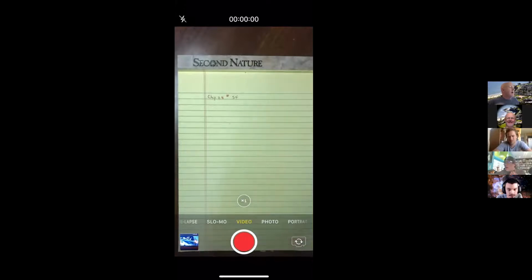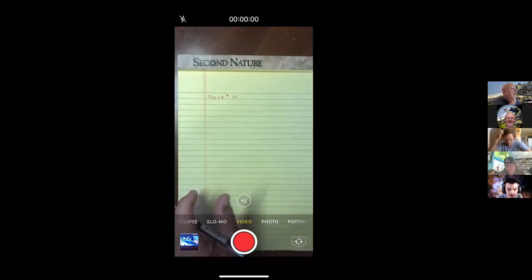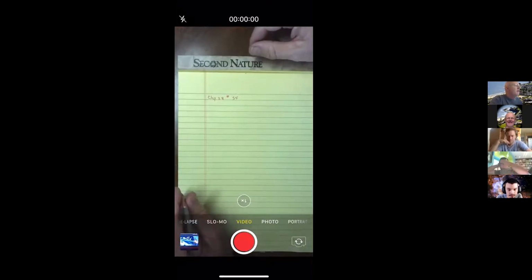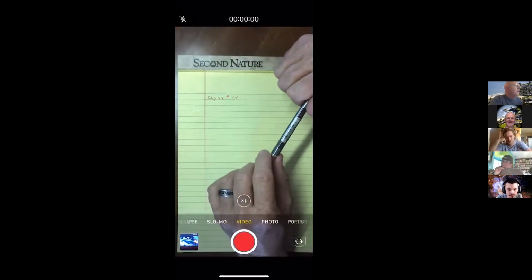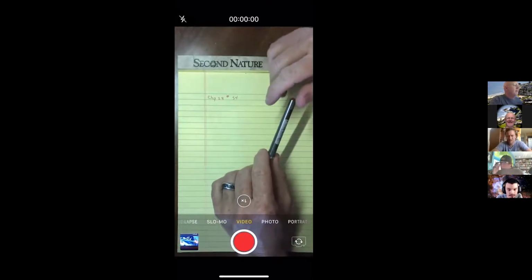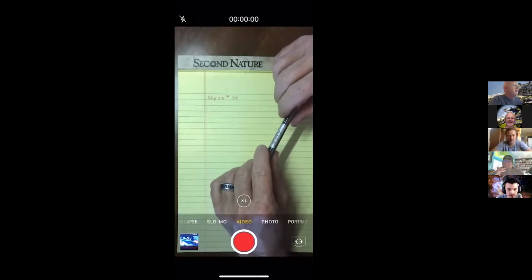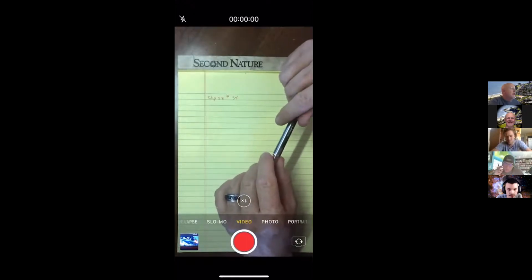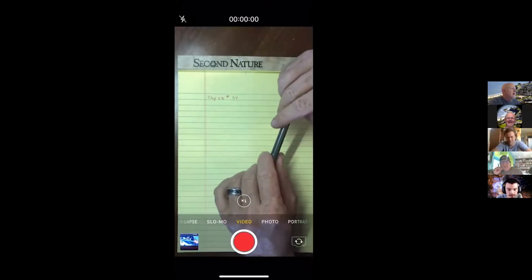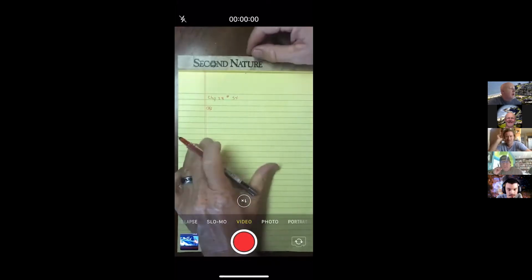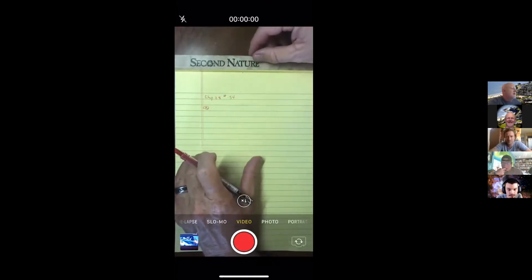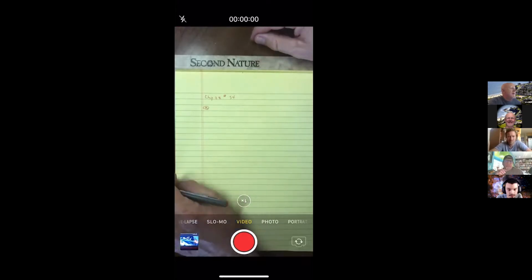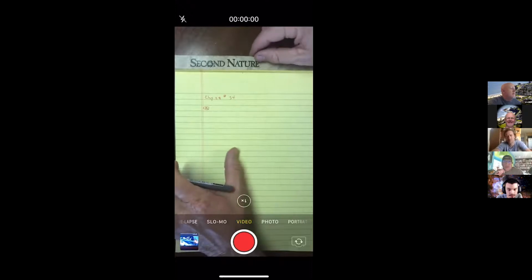Okay, 54. A young man owns a canister vacuum cleaner marked for 535 watts at 120 volts and a Volkswagen Beetle, which he wishes to clean. He parks the car at his apartment building and uses an inexpensive extension cord that is 15 meters long to plug in the vacuum cleaner. You may assume that the cleaner has a constant resistance. If the resistance of each of the two conductors of the extension cord is 0.9 ohms, what is the actual power delivered to the cleaner?